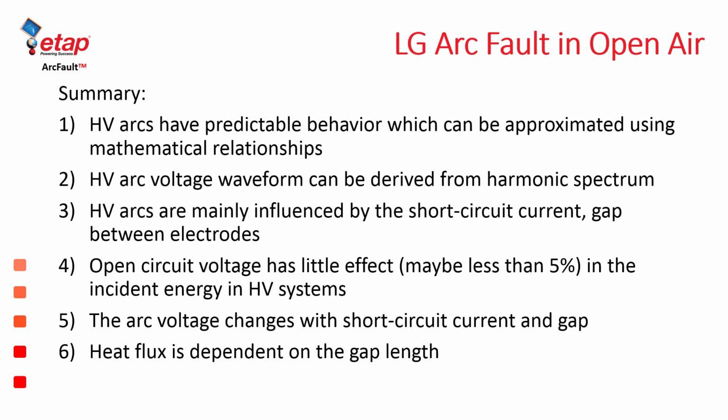To summarize this arc physical behavior, we can only take some of the key points that we have discussed. To actually learn all the arc physics and the details of the model development will probably take us a few hours. However, we can summarize that high voltage arcs have predictable behavior which can be approximated with mathematical relationships, and we can derive empirical equations from such.